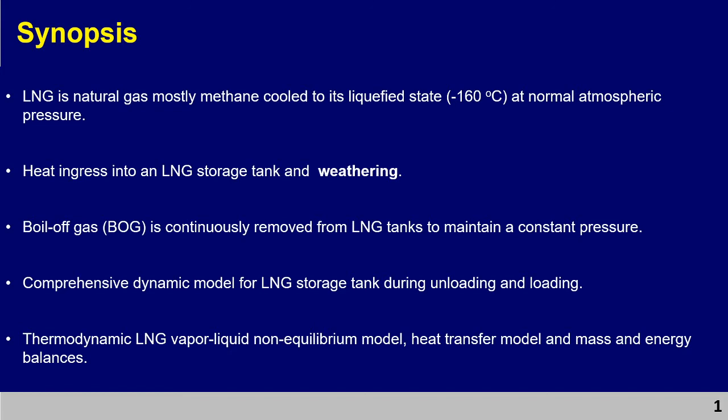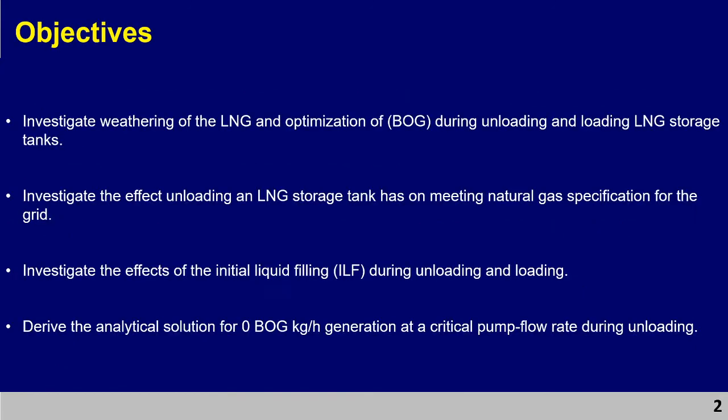Now, the vaporization, also called boil-off gas, needs to be continuously removed from the tank to maintain constant pressure. A comprehensive dynamic model was used to simulate unloading and loading of the tank. This model integrates the thermodynamic LNG vapor-liquid non-equilibrium model, a heat transfer model, and the mass and energy balances that were modified in MATLAB.